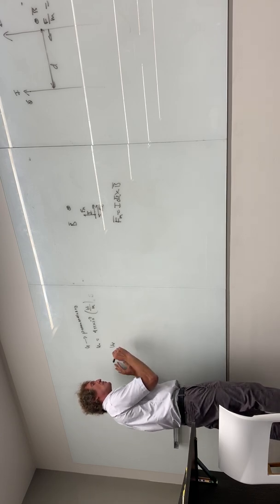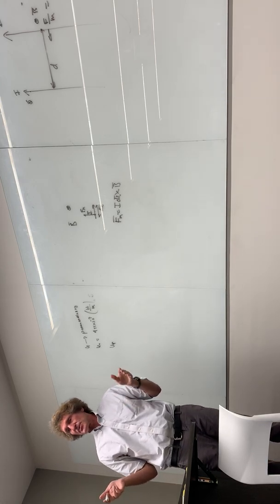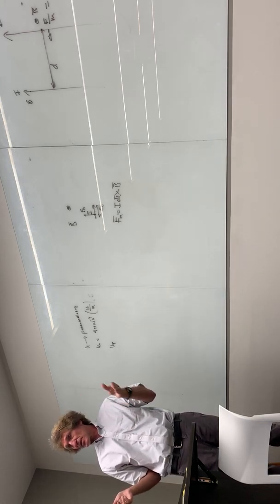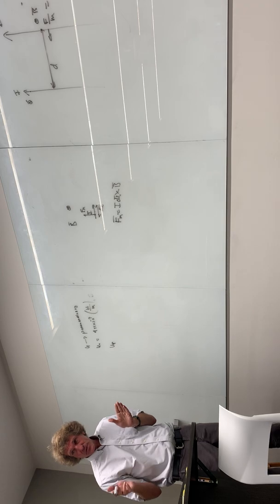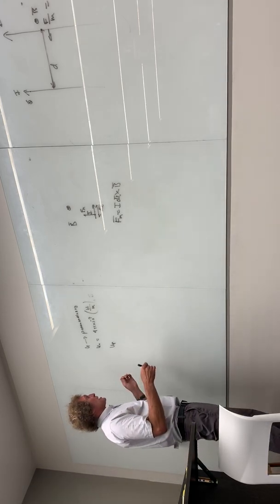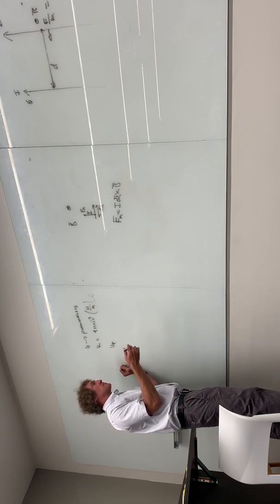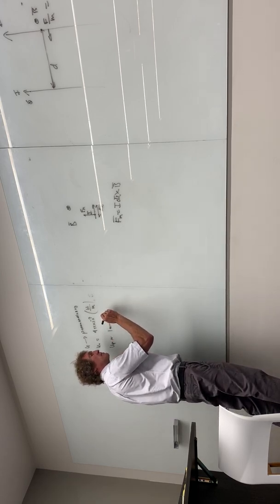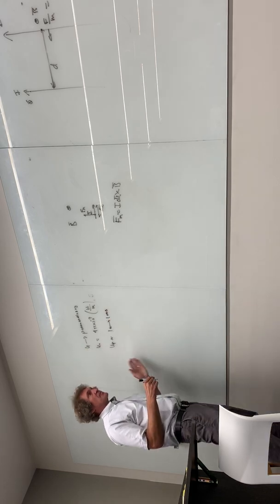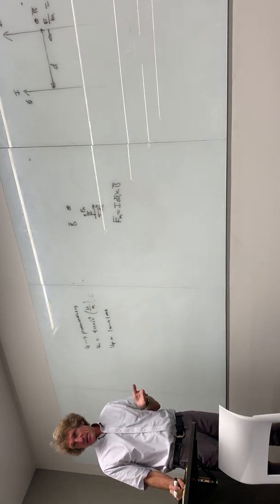And then they have something called mu relative also that talks about a material's ability to store magnetic energy. You remember epsilon relative had to do with the material's ability to store electric energy? The larger epsilon relative is, the more energy could be stored per unit volume for a given voltage across the plates. And with mu relative, it's how much more magnetic energy you can store relative to free space. Mu relative is typically from 1 to about maybe 1,000. There are exotic materials where it gets up to 50,000, but it's like epsilon relative. It's not 5 orders of magnitude bigger than 1, but it's somewhere between 1 and 1,000.